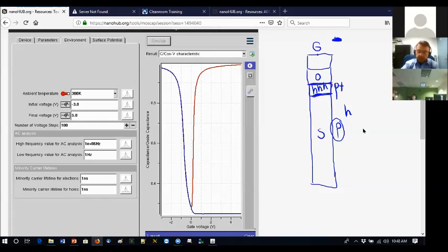That is what we will call the accumulation. The names are not super critical, but what will happen in the end is if I were to measure a capacitance here, the capacitance would totally come from the oxide. And you know how the capacitance is found. It's epsilon times area over D. If you do not remember the simple formula, let me remind you that D is the thickness.